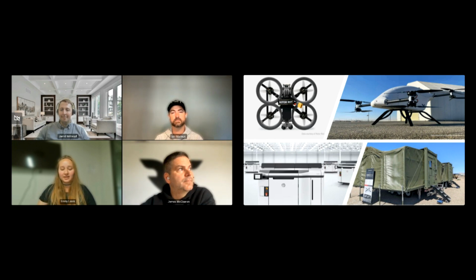And we're able to do that, like I said, through computational tools, but also through some of the features of the technology. Some of the things our drone team has been working on at HP is ultra lightweight wings, by really reducing the skin thickness and then having a more complex ribbing pattern in the surface that gives it rigidity, even though we're only printing at a fraction of a millimeter in skin thickness. And so in one area, they've been able to optimize for their application.